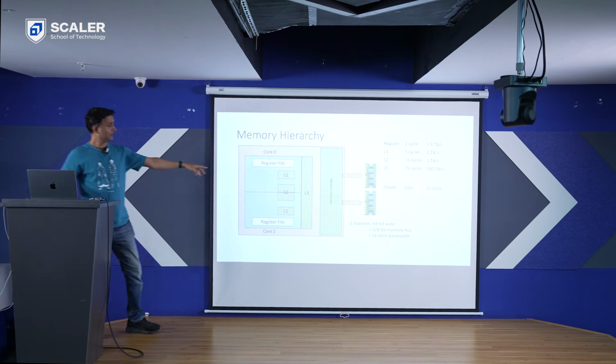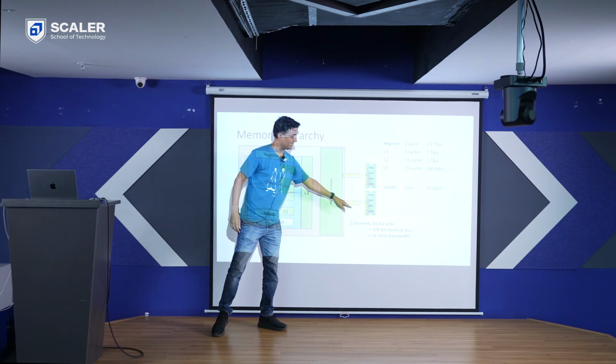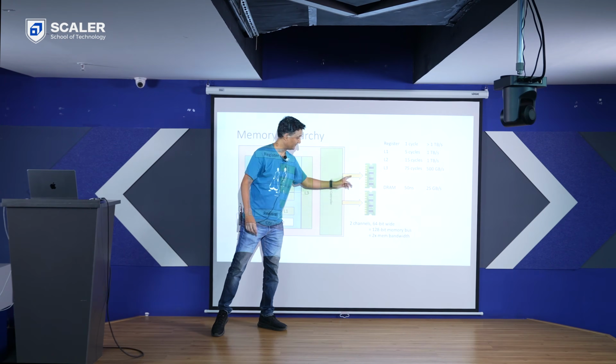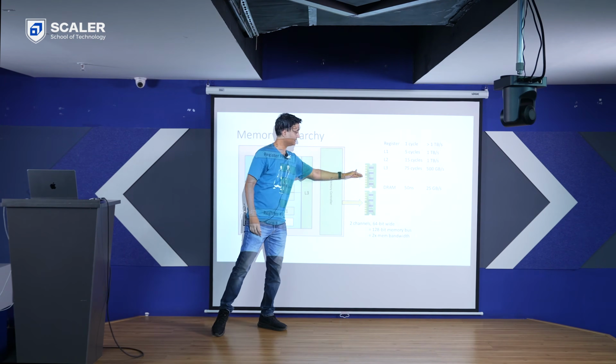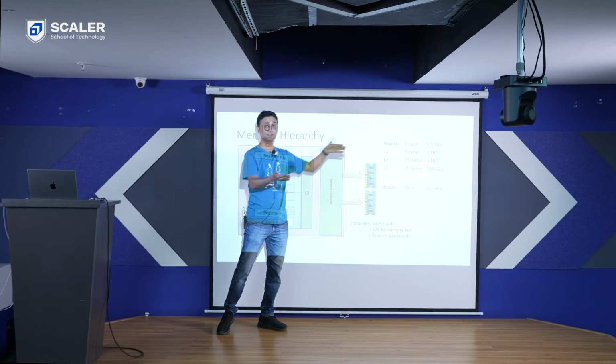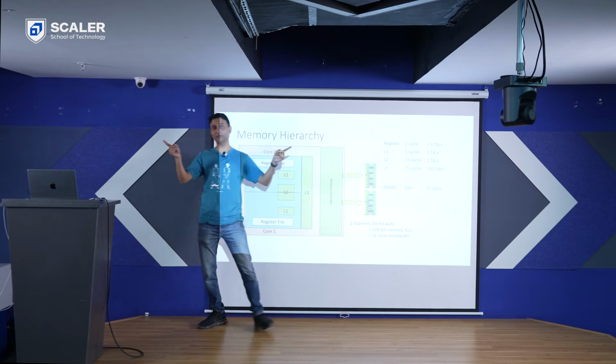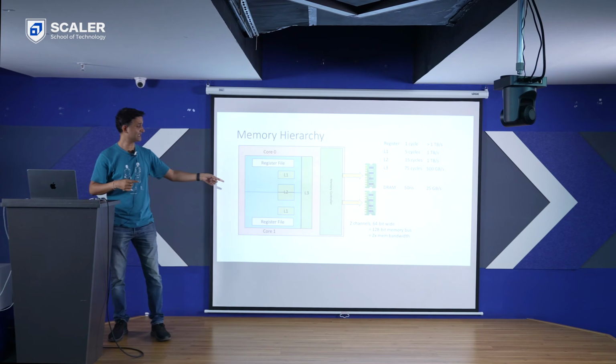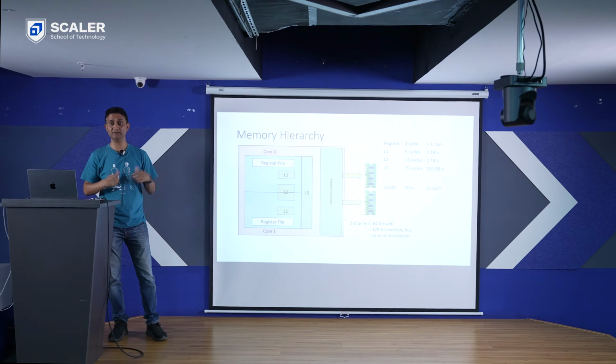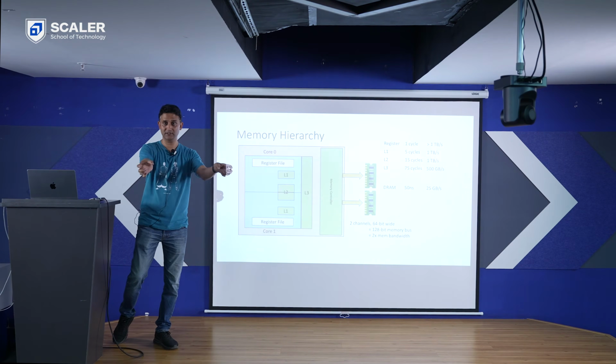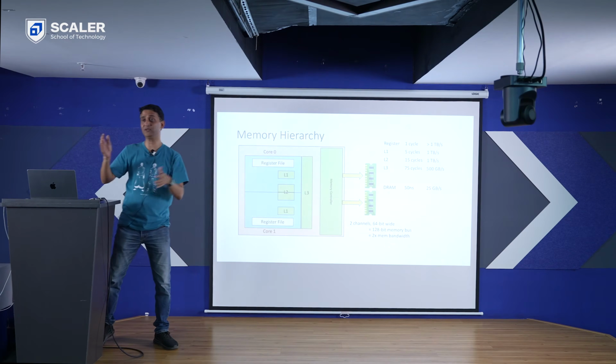This is usually 2 channels. Somebody was talking about channels. This is what a channel is. Here, and this we can actually do in parallel. It gives us more throughput. We refer to this as a 128-bit wide bus. The moment we've got two 64-bit channels, we refer to this as 128-bit wide memory.